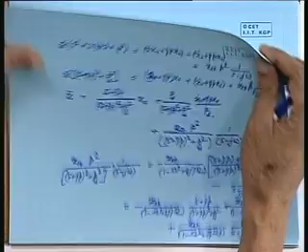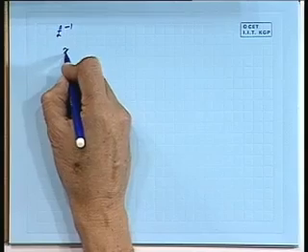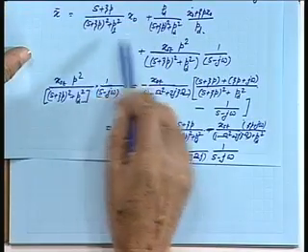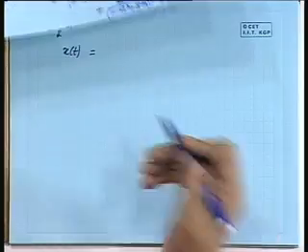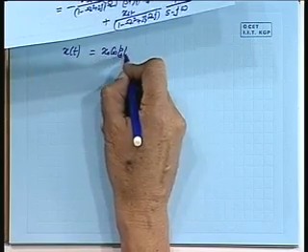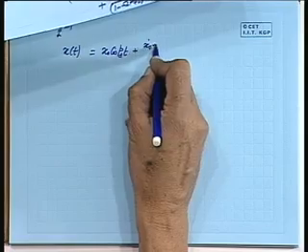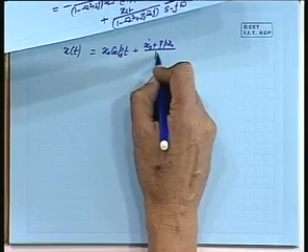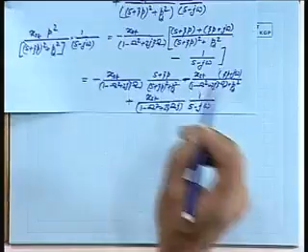Now, you take the inverse of this. What you get is x of t: the first term, which is this here, gives you x0 cos pd t. This term will give you x0 dot plus zeta p x0 over pd times sin pd t.